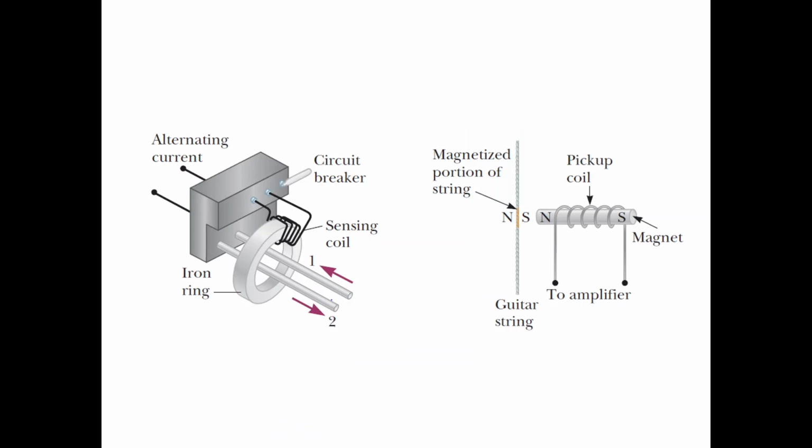There are different applications of Faraday's law and induced electromotive forces. There are so-called protective electric circuit breakers. There are different kinds: one protects from short circuit, so if you literally short circuit your power outlet, current increases beyond some threshold level, and the circuit breaker opens the circuit so you don't burn the house.